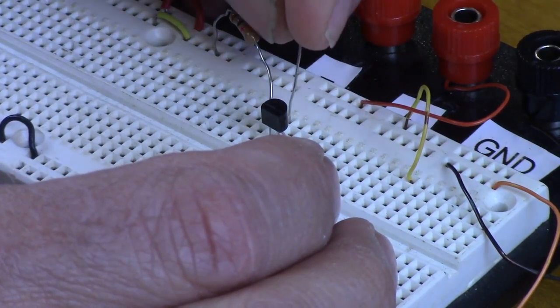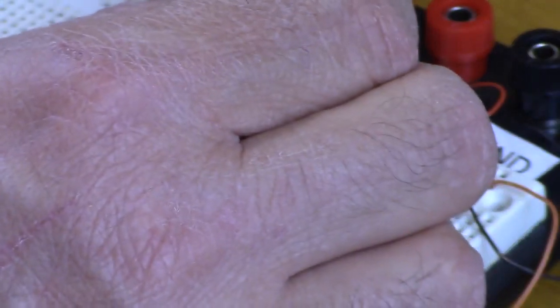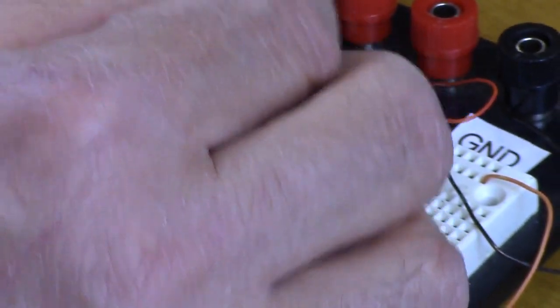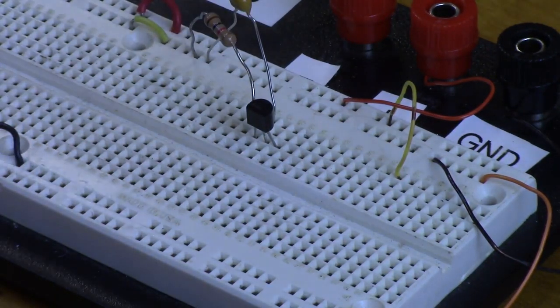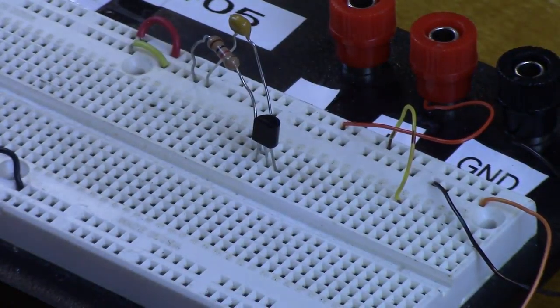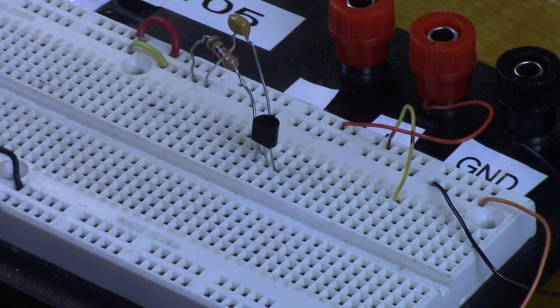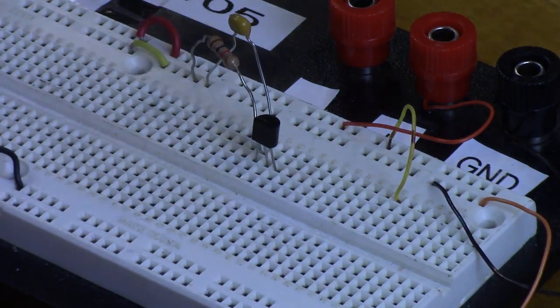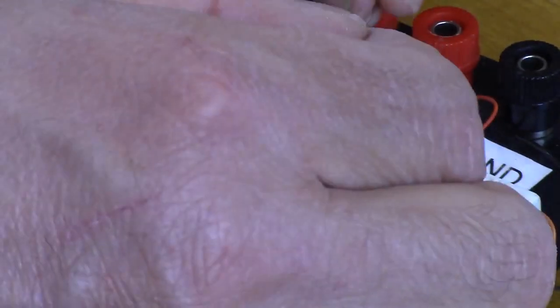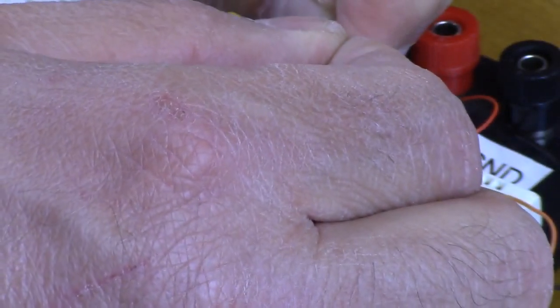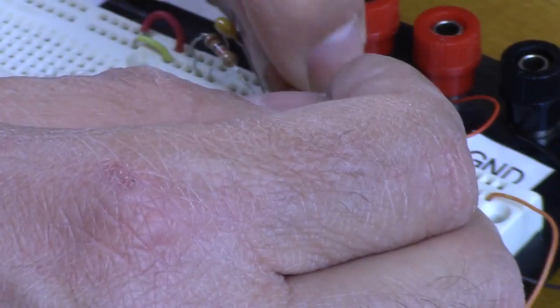So it looks like we're just building this one from the bottom up. Now the capacitor is tied to ground, but just a point of trivia, you could plug this capacitor into VDD and it would still do the same thing. Okay, so we have our R1, a 100K resistor going from the base up high, base to our VCC, the upper bus.